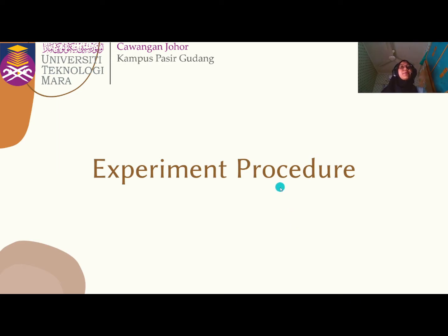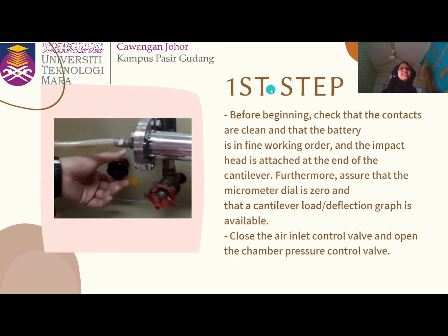For the experiment procedure, before beginning the experiment, check the contacts. The contact should be clean, and the battery also should be working fine. The impact head is attached at the end of the cantilever, and furthermore, ensure that the micrometer dial is 0 and that a cantilever load or deflection graph is available.